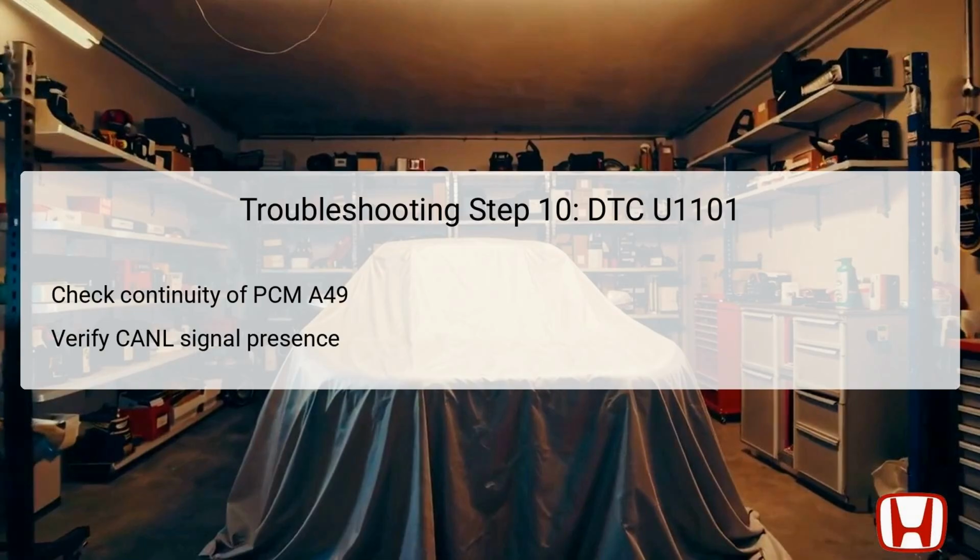If the connection is present, it indicates no circuit interruptions, supporting the hypothesis that the FCAN architecture is functioning correctly at this junction. However, if no continuity is identified, this may point to another technician intervention area, necessitating further inspection of the wiring and connections that may be faulty or damaged.